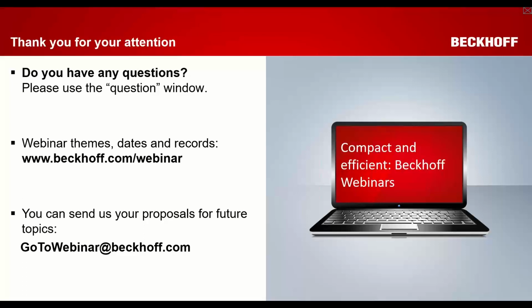The first question is, how can we change from a library to a reference library? This question is regarding the library management and the new reference libraries. It is actually pretty easily possible. If the library is added as a dot library and not a compiled library, there is even a very integrated way of just right-clicking onto this library and selecting to switch to the reference library. Then this library would be used as a basis to load the library project.